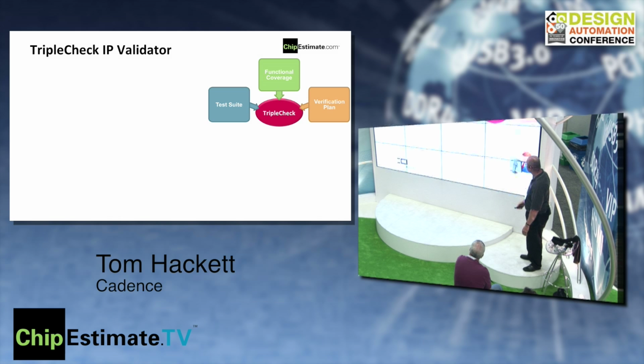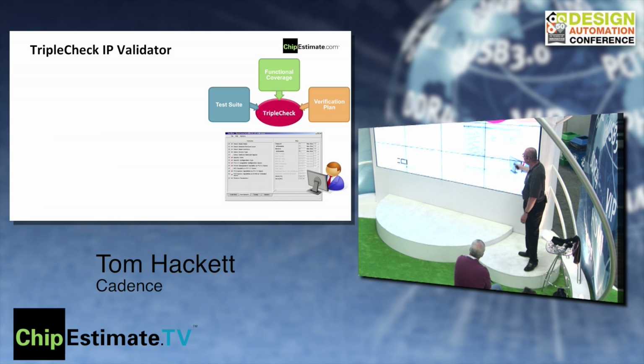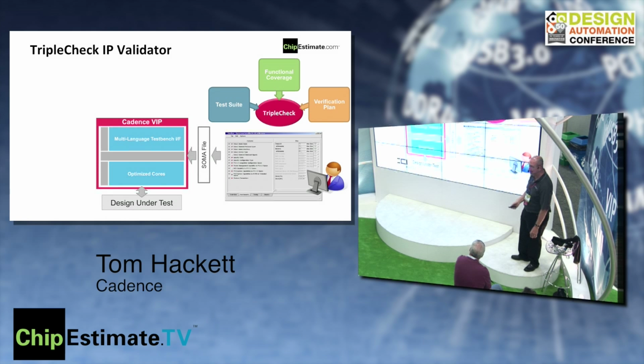And so the user sits at his console and opens up a GUI that helps to configure the VIP to match the design under test. So let's say, for instance, that your design is a PCIe root complex. So you need to set up the VIP to be a PCI Express endpoint.